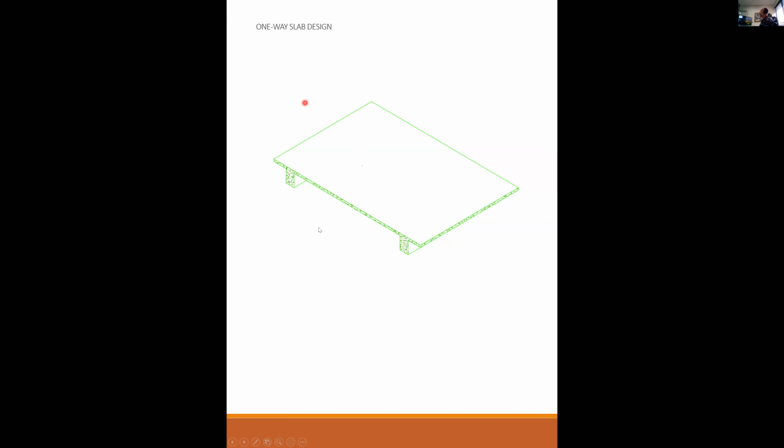This is just a cutout of some typical concrete flooring system. And the concrete is all monolithic, notice. The beams and the floor slab are all the same pour of concrete, but the thinner section spanning from beam to beam we call a one-way slab, and then the beam sections themselves are the beams spanning probably from column to column, okay?